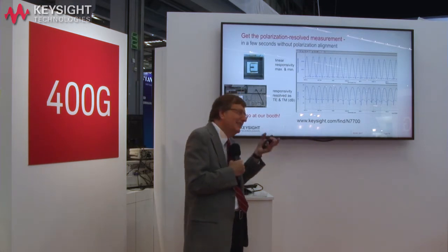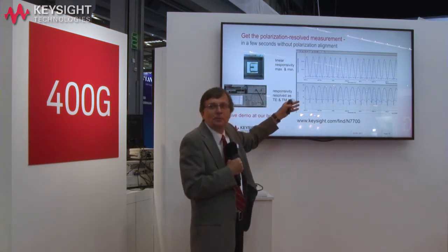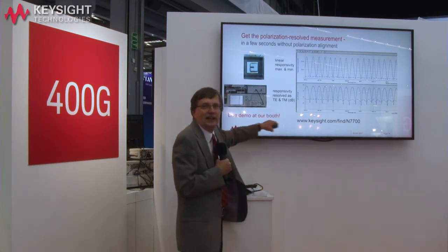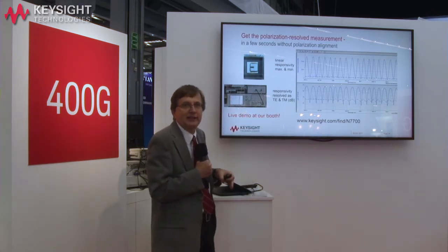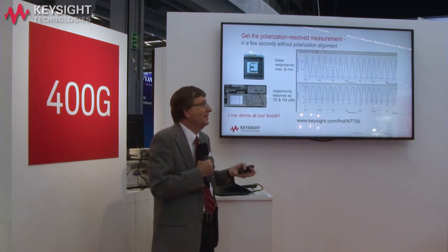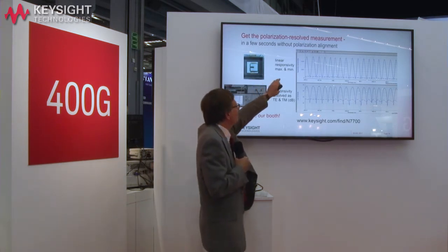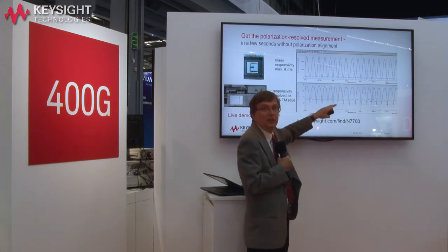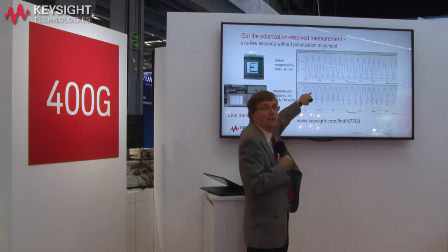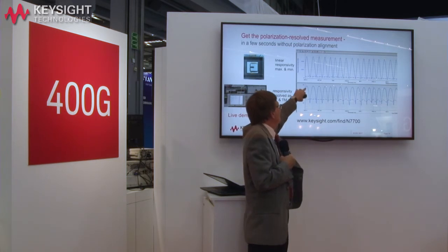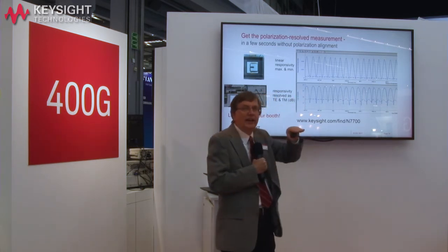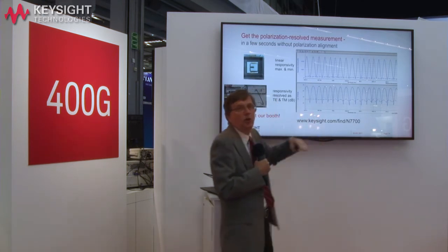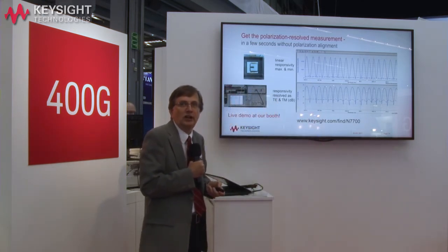the signal, that's going to be really sensitive to, and we're not going to get a nice flat curve across wavelength either. But now if we make the measurement, we do get that. We get something that looks flat across wavelength. We get the whole thing without having to tune up. And you can see that there are places actually where the polarization state in the one axis crosses the one below, but we can sort that out as well with our software.